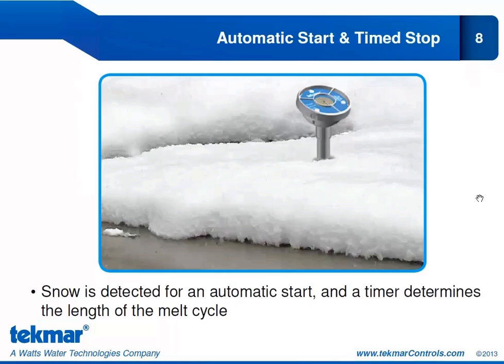Now there are definite advantages to this. It is an automatic start, so even if you are asleep or at work, your snowmelt system can work when needed. Of course, the disadvantage to the time stop is what we talked about before, in that it is difficult to predict most efficient length of melt cycle.